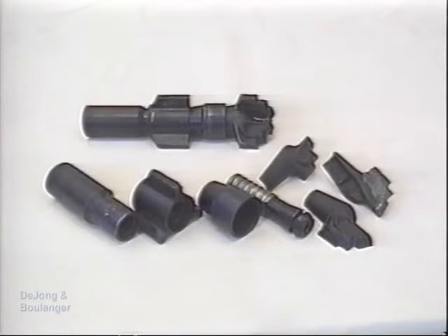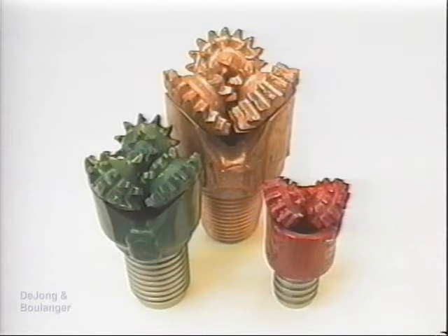The replaceable drag bit, one of the most common, consists of a barrel, bowl, blades, and connectors. This design is economical since worn teeth can be replaced rather than replacing the entire bit. The cone bit has teeth on the surfaces of cones, which rotate as the bit is turned. The spacing and size of the teeth on the cone depend on the type of material to be drilled.